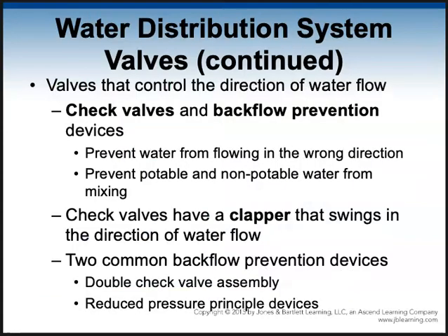So these valves also can control the direction of the water flow. And there's check valves and backflow devices. We don't want that dirty water going into our drinking water. So backflow devices keep that water from going back. They have clapper valves that swing in the direction of water flow, and they'll only let water go in but never back out.